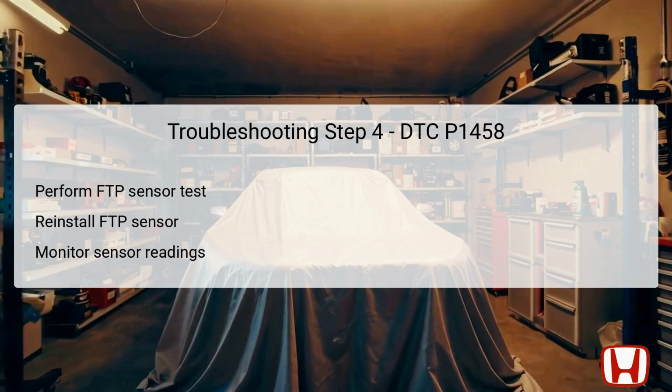In the fourth step, focus on performing a functional test of the FTP sensor. After reattaching the 3P connector to the FTP sensor, switch the vehicle's ignition to the on position, but do not start the engine. Monitor the readings again using the HDS for the FTP sensor.